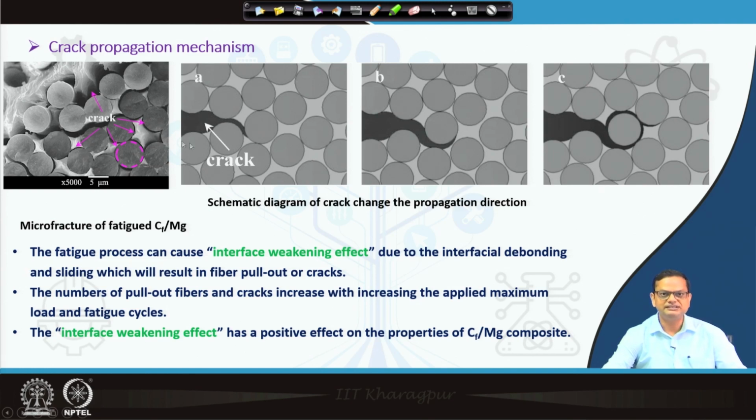However, these interfacial cracks are not through. So, there will be interfacial cracks and crack bridging. You can see the crack forming and then going through the interfaces at different stages, I mean different fibers. So, it is like a never ending process. The crack is never through the material, and that is the reason the fatigue resistance increases.